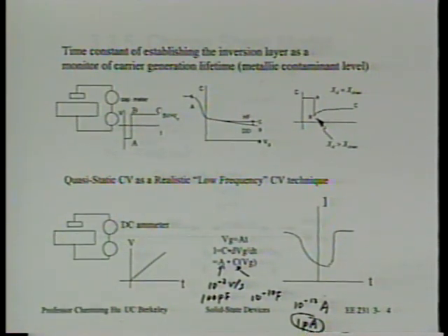You cannot do that on very small capacitors. When the capacitor is too small, use a somewhat larger test capacitor, then you will be able to measure this. Are you following what I'm saying? Okay. So therefore, this is how we actually measure the quasi-equilibrium capacitance. This is what most people will think of as the low-frequency capacitance, but it cannot be measured by using low frequency. All right? All right, good.